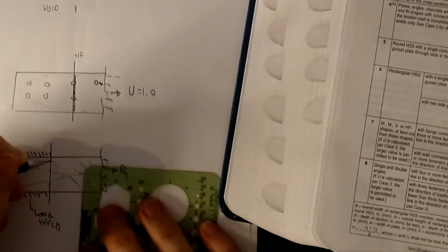This is called a longitudinal weld. Okay, and if we imagine our flow net diagram on this, this is very similar to what we were seeing with the I-beam, that some of the load, if we start to think that maybe it goes to that back corner, this becomes my effective area on there. But we do have a big dead zone in here that's not. So if I were to think that this is my net fracture plane on here, well, then I'm looking at an area that's here, and an area that's there as being the loaded area. So this would not be a U of 1.0 case.